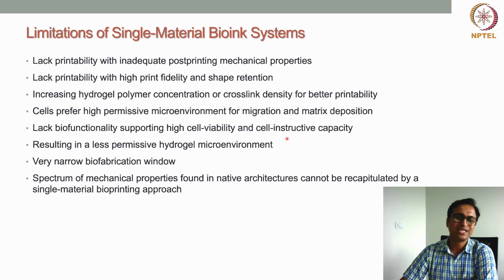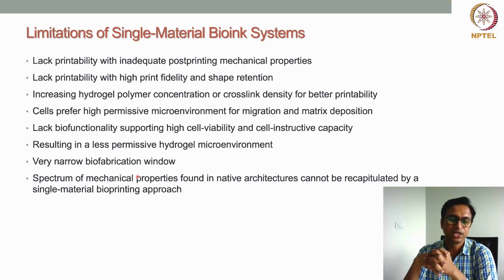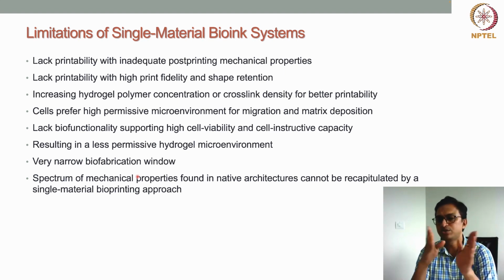That's why with a single material Bioink system, we have a very narrow biofabrication window, because we cannot use a very low viscous Bioink. When the concentration of the material in the ink is low, the viscosity is also low, and that is not good for printing.